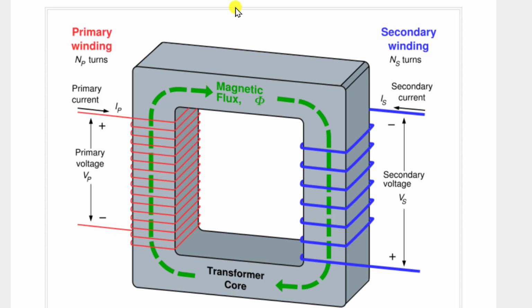Alright, so this is what we call a step-down transformer, in that it is reducing the voltage, and that would increase the current. Anywho, let's assume that this is from your high voltage lines. The high voltage line would have a wire that comes in and wraps around an iron core, and then it goes back to the high voltage lines on a return wire. So this has to be AC electricity, push and pull, push and pull. Inside of these loops of wire, that's going to make a magnetic field, and this iron core amplifies that.